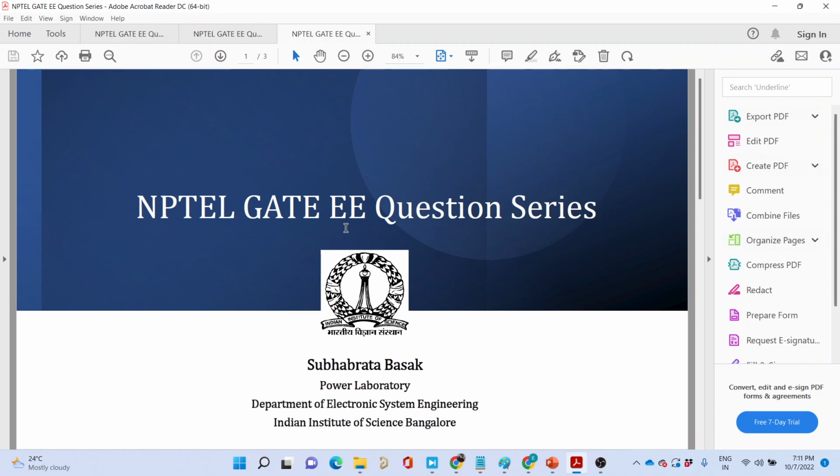Sir, how did you know zeros contribute to the lag? If there is a zero, say s plus 2, what is the angle contributed by zero? Tan inverse of omega by 2. There is plus tan inverse of omega by 2. That is lead, not lag. Getting my point or not?